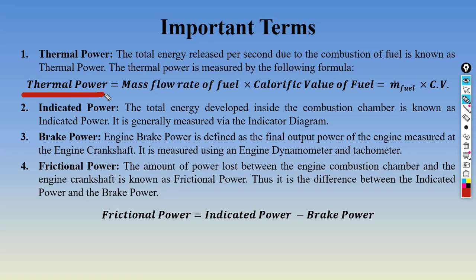So thermal power is what? It is the mass flow rate of fuel. In 1 second, how much fuel is flowing inside the engine, multiplied by the calorific value of that fuel. So that is your thermal power.